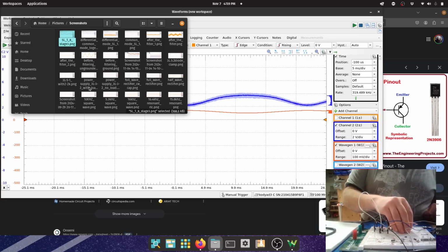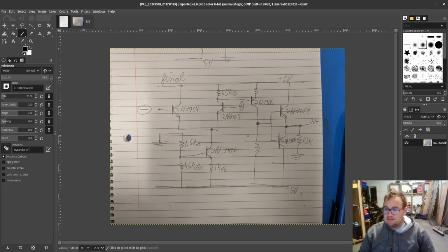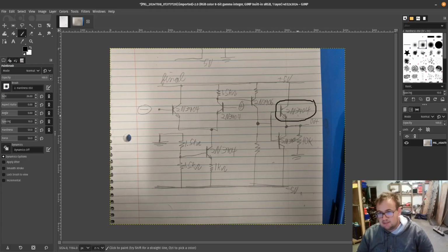Okay, so let's assemble the last stage of this op amp. I just wanted to say what changes to our little circuit are done in section 5L.1.9, which happens to be the final adjustments to our circuit. So first, put in these two transistors: this NPN one, 2N3904 right there, and this one here too, that's a PNP 2N3906.